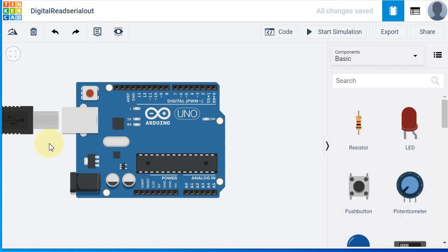In the same way, analog input and output vary not in a static manner but continuously from 0 to 5 volts. The analog input or output takes place on A0, A1, A2, A3, A4, A5 of the microcontroller, and the digital ones go on D0 to D13. On the Mega, there are some more pins.